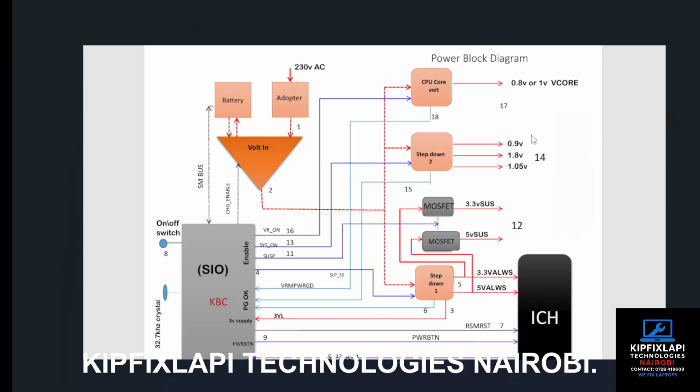Yes, in my previous video, I explained about the voltages of different RAMs. In case I had, for example, DDR3L, I would have had, sorry, this is not DDR3, this is DDR2 because of the 1.8 voltage. DDR3 or PC3 has 1.5. So this one is PC2. It has a terminating voltage of 0.9, operating voltage 1.8.